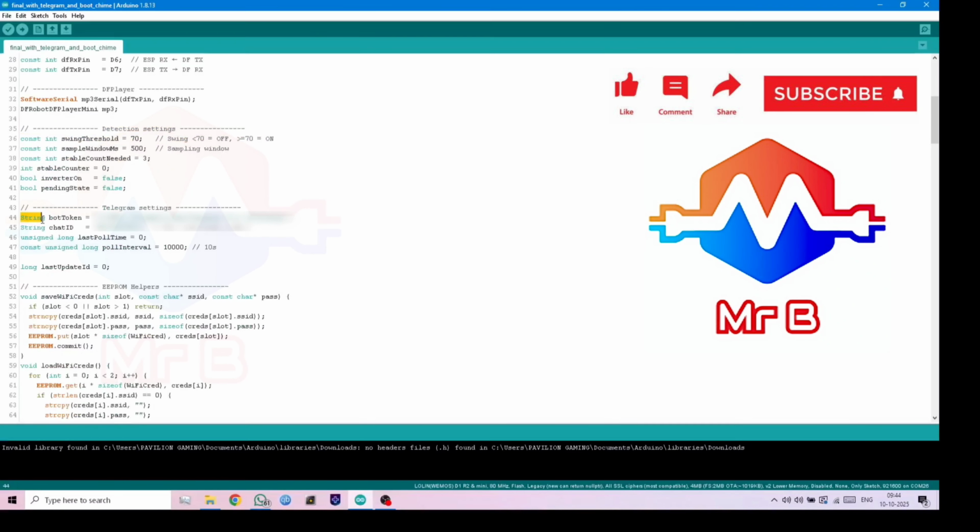Then we have got the Telegram section. So this is the bot token over here that you will get after you have generated your Telegram bot, and then you have to put in your chat ID, that is your exact Telegram account. It has got a chat ID which is unique to that, so you need to put in that so that the bot that you have created can talk to you via your personal Telegram account.